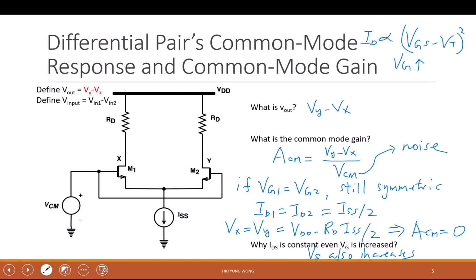In an ideal scenario, wouldn't the voltage before and after the current source be the same? Ideal scenarios are before and after. You see this one? Current source doesn't care about the voltage across it, right? It only cares that you deliver a constant current. Do you remember this ideal current source that we always draw? The current is always constant, regardless of what is the V across it. Good point.